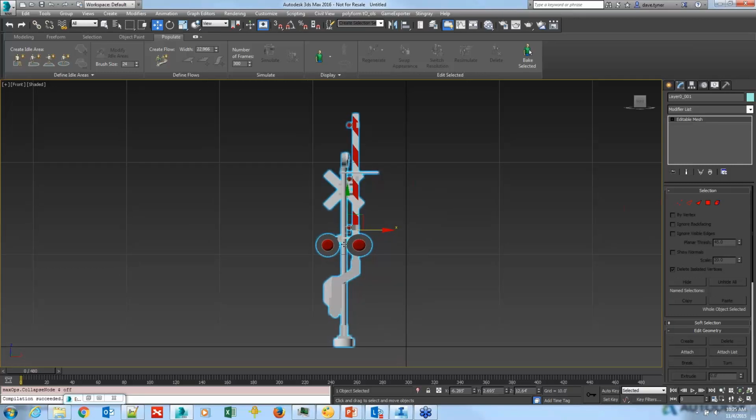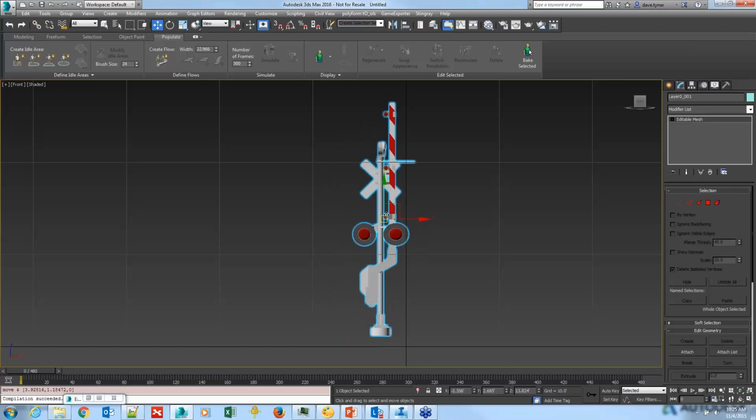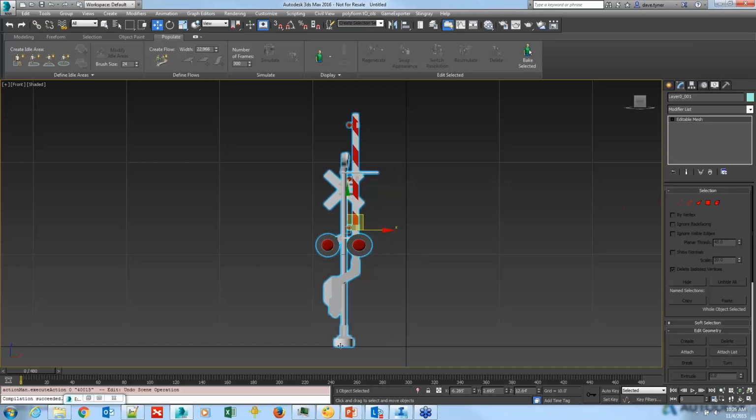And then one thing here that's not in the presentation, that I just like to do because it's best practice, is to move this pivot point, the origin point of the object, down to 0. The way we do that is right here on all of our panels we have this hierarchy panel.